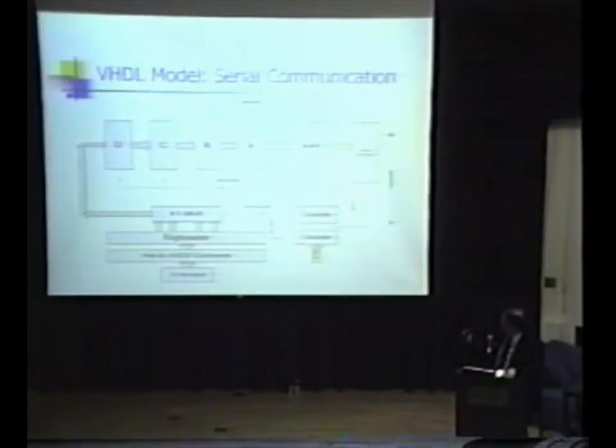It first starts out with a hex ASCII converter, which will convert a 12-bit input into hex so it can be shifted out. Then it is inputted into a MUX, transmitted through these registers, and out through a shift register to HyperTerminal. And this is all the control logic right here that controls the MUX and these registers.